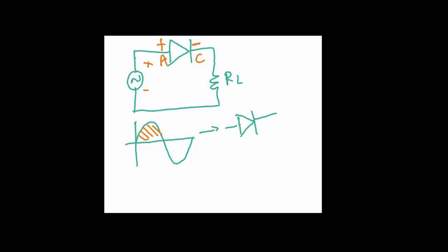During the positive half cycle, let's say the input voltage you apply is 5 volts peak. So that's 5 volts, and this one is negative 5 volts. As the input signal goes from 0 to 5 volts, remember this is a silicon based diode, so you need to overcome the barrier potential or the forward voltage drop of the diode. If it is silicon, it is 0.7 volts. So if the input is less than 0.7, the diode is still not conducting.